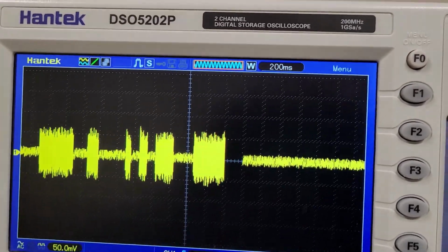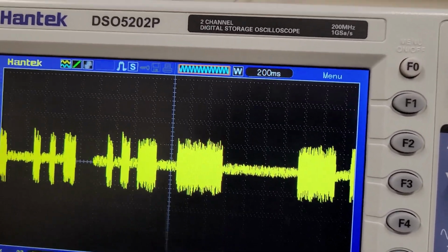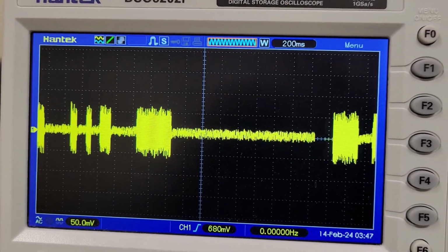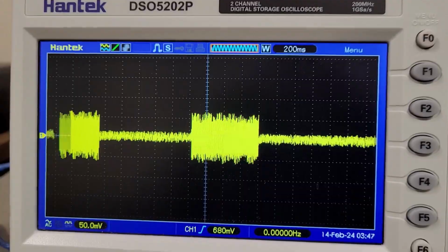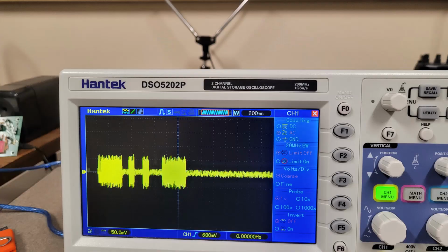The next question says, what signal source is connected to the vertical input of an oscilloscope when checking the RF envelope pattern of a transmitted signal? The way I did this video was coax connecting the input of my oscilloscope to the antenna switch. I did not have the transceiver connected to the oscilloscope using the antenna switch. Instead, I had the transceiver connected to the antenna. But there's enough stray RF in the switch that it could sample that RF and output that to the oscilloscope. So it's a way of using an attenuated RF output.